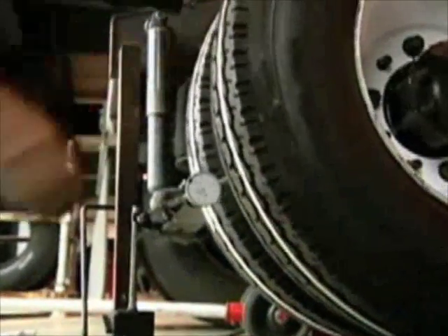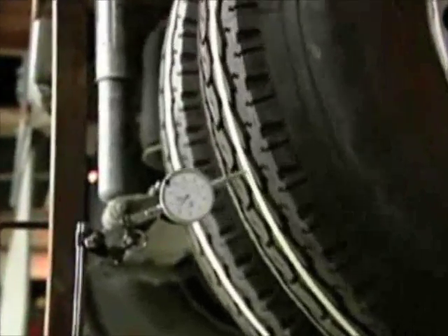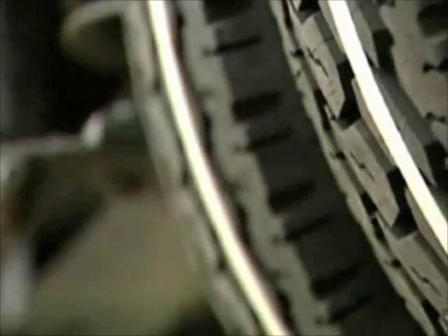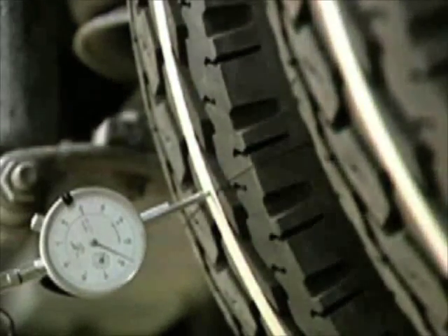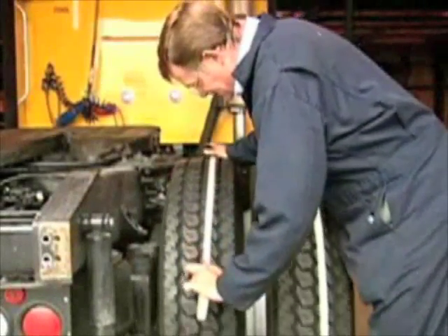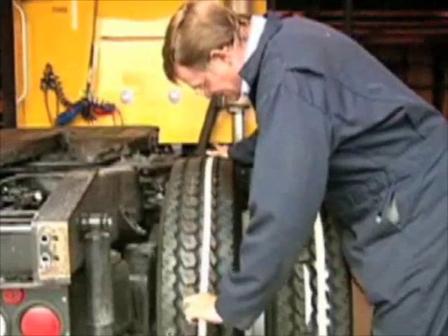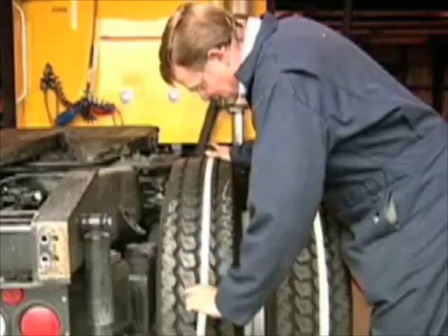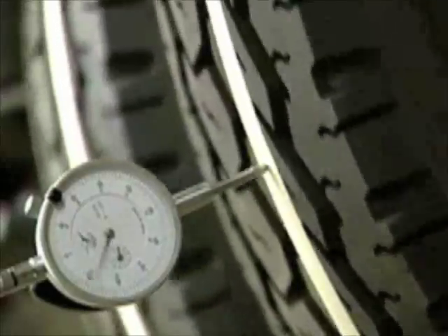If you need to check radial runout on dual drive axle assemblies, check both the individual radial runout of the tires and wheels and the comparison of the high and low readings of each tire and wheel. Note how they match or offset each other. Keep in mind that if traction or lug-type tires are used, it will be easier to obtain an accurate radial runout reading by applying tape around the tire circumferentially. This will lessen the high-low hopping of the tread pattern on your gauge.